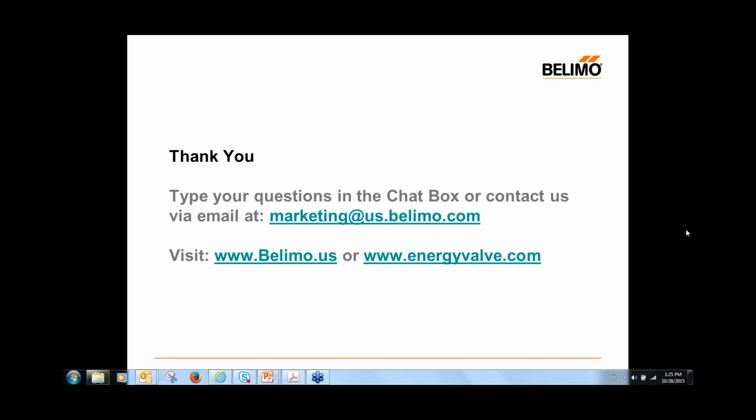Okay. Doesn't the delta T manager sacrifice AHU discharge temperature to maintain set point accurately? No, it does not. Based on how we calculate BTU yield from a coil, there's a common formula, 500 times GPM times the delta T. So if we go beyond our design flow and beyond our design delta T, or below our design delta T, we simply swap the numbers around and still wind up at the same BTU yield. So to say more flow will also correspond with lower delta T, we will not yield additional BTUs. Therefore, we won't have any effect on discharge air.